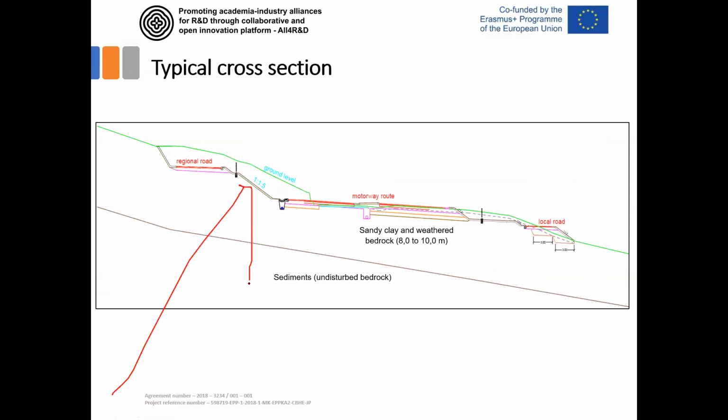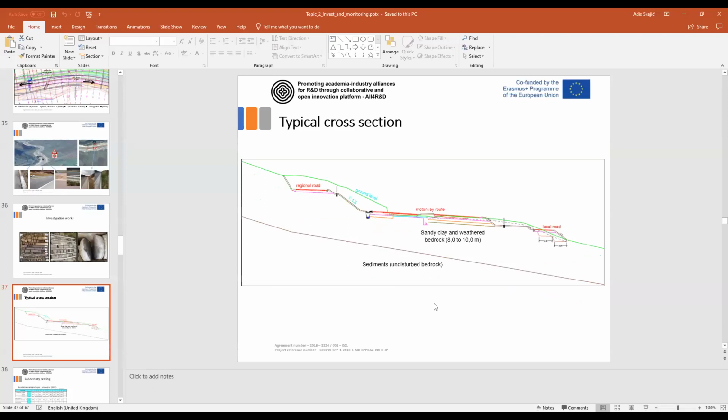So when we construct the inclinometer, it should go like this. Here it should go as deep as possible. Typical guidance for the depth of boreholes in landslides: go and reach the stable area. The stable area must be defined in situ during the drilling operation. You can recognize it as a very large resistance to drilling.